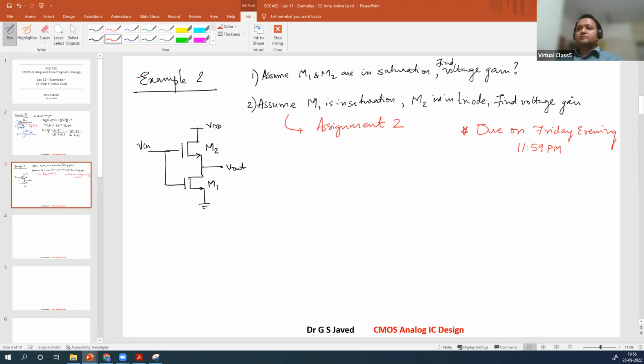How do we do the first one? The previous one we did not draw the small signal diagram. Now let us draw it here. Just a quick refresh. So what does this look like? Input is given to both here and here. Correct? So an important point is gmb, here it is ground. So here VSB equal to 0,